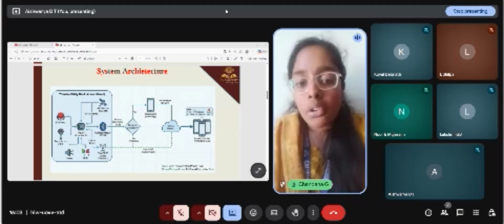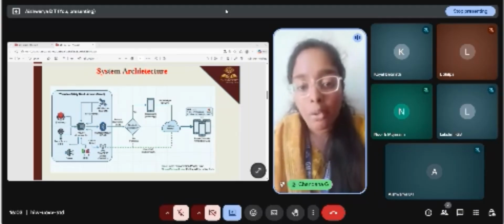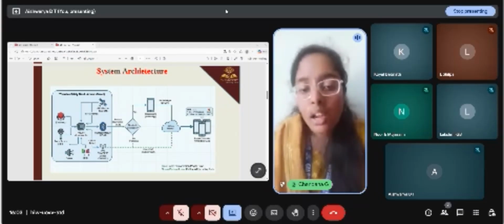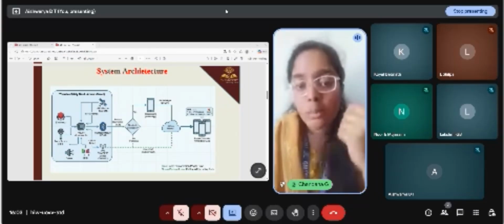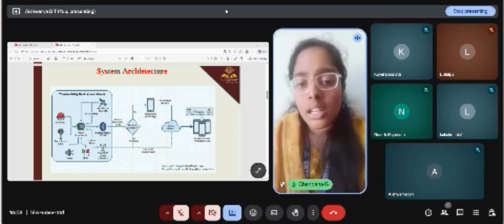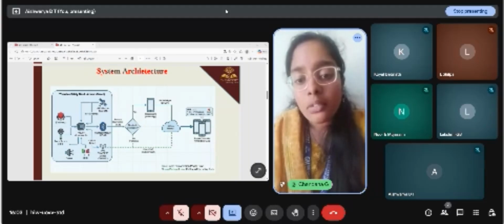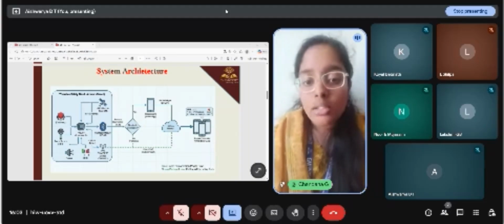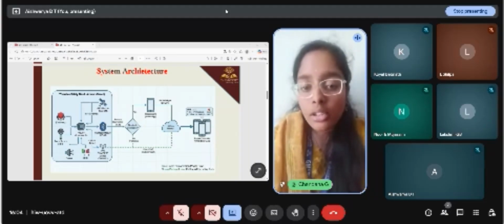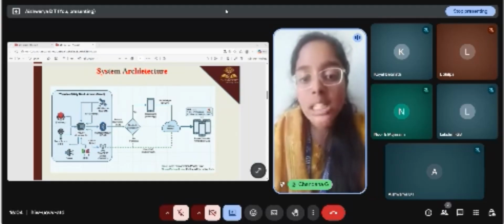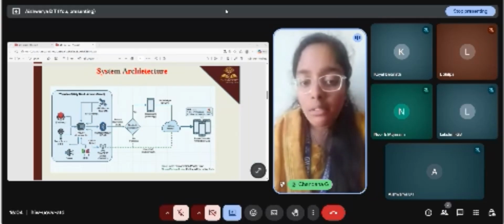The entire process works without Bluetooth or mobile app support, and we will further implement a Bluetooth connection. And why we did not introduce Bluetooth here: Bluetooth requires constant pairing, connection failures may occur, and the smartphone must be nearby and active. So it causes delay during an emergency. GSM provides direct and reliable communication and works independently of smartphones.